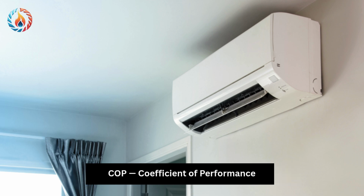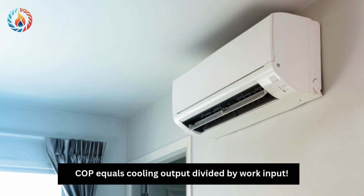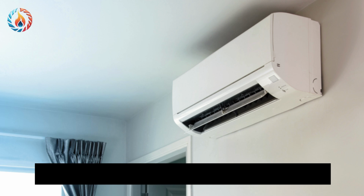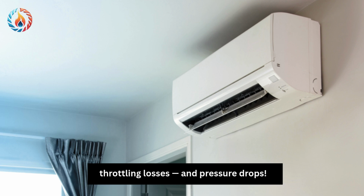COP, coefficient of performance. COP measures the efficiency of the vapor compression cycle. COP equals cooling output divided by work input. A real refrigeration cycle always performs worse than the ideal because of irreversibility, heat transfer limits, throttling losses, and pressure drops. Higher COP means more efficient system.